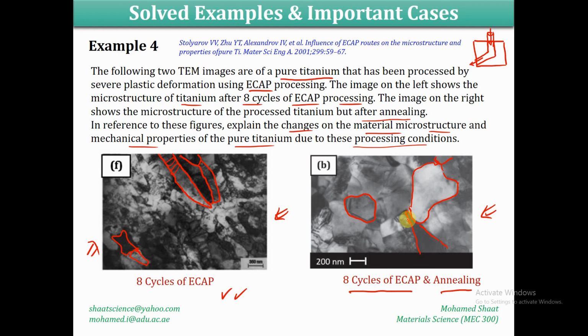It is dark, that indicates that it still has some dislocations, and also this is dark. But the other grains have almost the same contrast, but still they do have some dislocations, because these dark things and colors indicate that there is a dislocation inside the grain. But this also indicates that the amount of dislocation has been severely and significantly decreased. It means that definitely we moved to the recrystallization phase of the material microstructure during the annealing process.